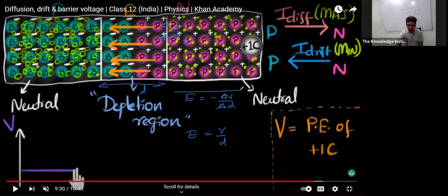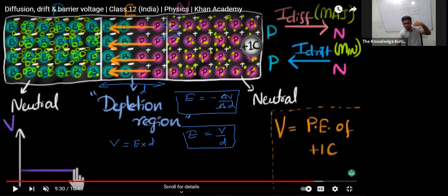So this part is there in the electric field lesson. You have to draw the variation of electric field by considering the potential gradient. Anyway, just considering the magnitude, we can write E equals V over D. Therefore, here V equals E times D. So this built-in electric field, once it reaches equilibrium, or if it is completely depleted, at that time this value E will be constant, and then the thickness of this will be constant. Therefore, this constant potential is known as the barrier potential.